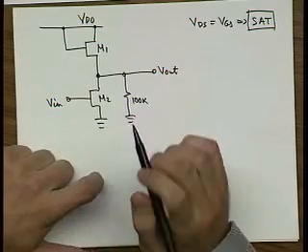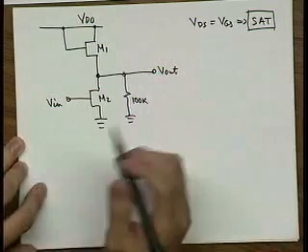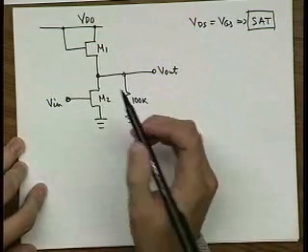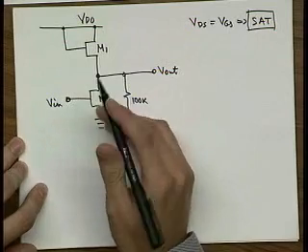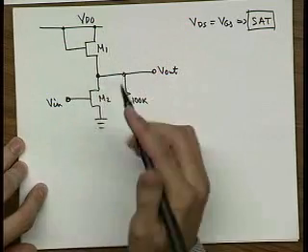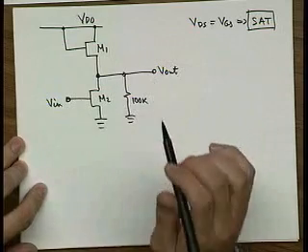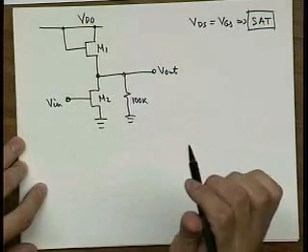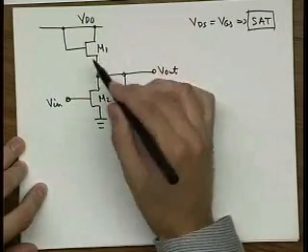So now let's start with calculation of VOH. And for that purpose, it's valid to assume that my VOL is going to be something that is less than the threshold of this device. Let's say my VOH and VOL are not really going to be at VDD and 0, because this is a little tricky configuration here because I have the side load.